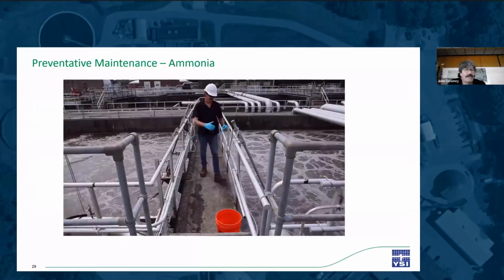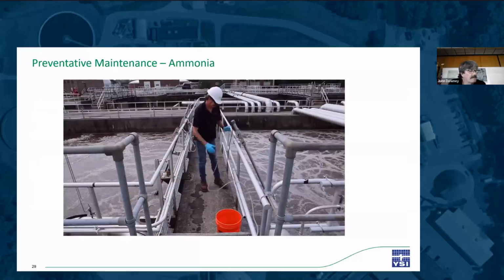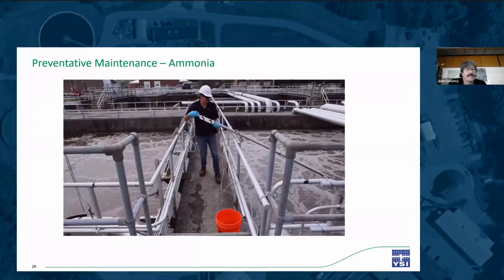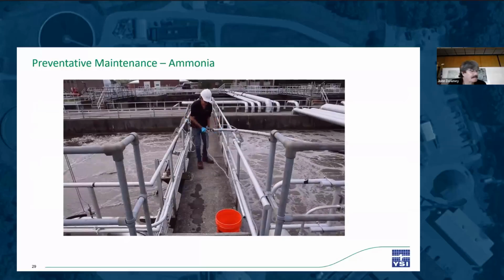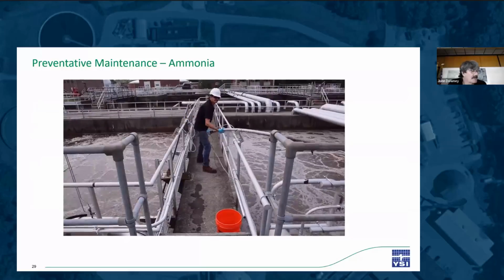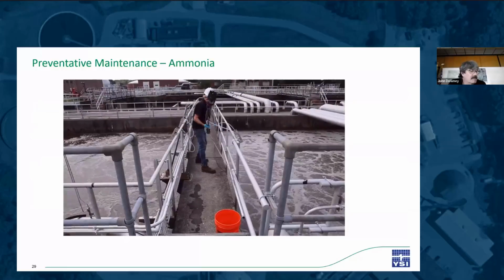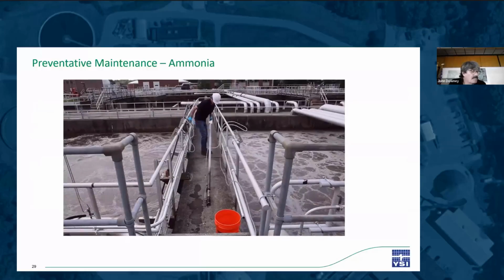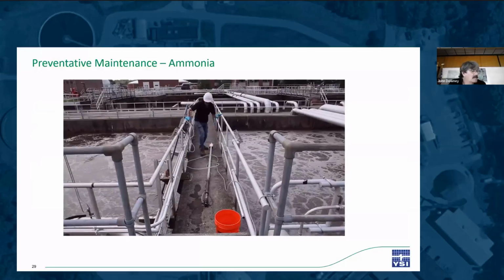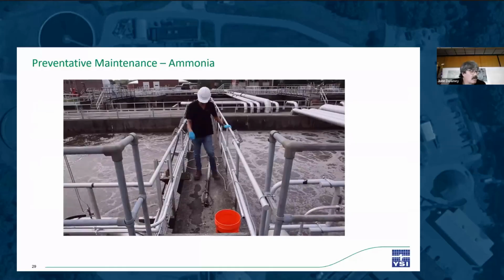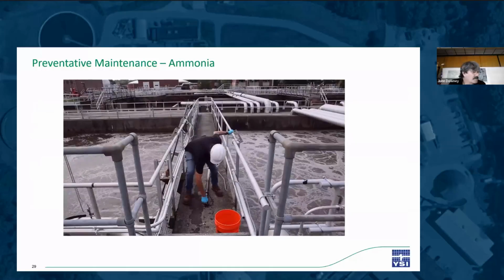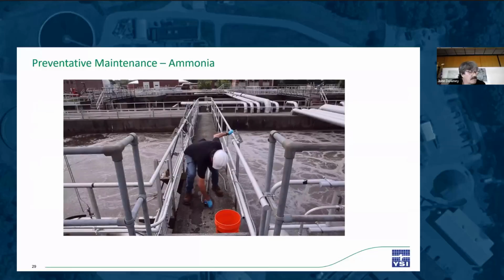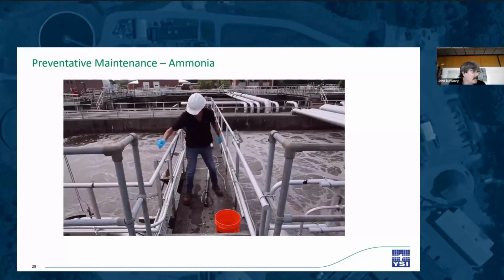When I do remove these from process for cleaning, as I'm doing in this slide, I use a damp paper towel and I'm careful not to be aggressive with the membrane. The most important thing I do with any of these sensors is to look at the curves for the previous 24 hours. It's a great way for me to know what's happening, pick up on something that doesn't make sense, or identify a specific point for attention. It's on that basis that I will select the nitrate or pH sensor for maintenance.